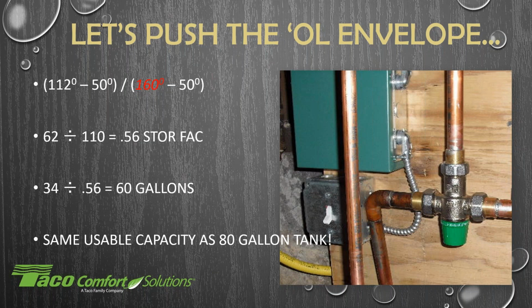Go ahead, John. You're talking about accumulation and scale. Yeah, there are a lot of factors that play into water heater life, the end of a water heater's life. Gas water heaters, a lot of it has to do with sediment building up at the bottom, and that the water heater's never really flushed out, and that stuff's never really drained out. So that creates a barrier between the water and the flame, and that heat builds up there, and that's what causes failures down at the bottom for gas water heaters. And a lot of people never really service the anode rod. The water heaters are considered throwaway items anyway, so they don't service the anode rod.